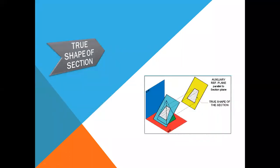Now, suppose we are sectioning a square pyramid with an inclined auxiliary plane. So now this is what the true shape of the section will be. What we will do is take a plane which is parallel to the section plane or section surface, and on that plane we'll get the true shape.